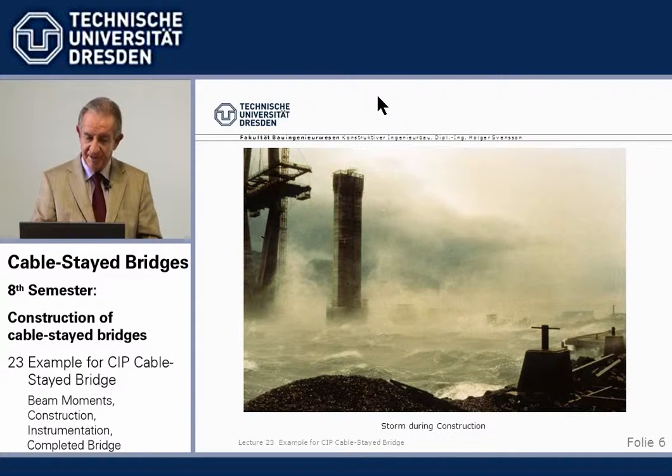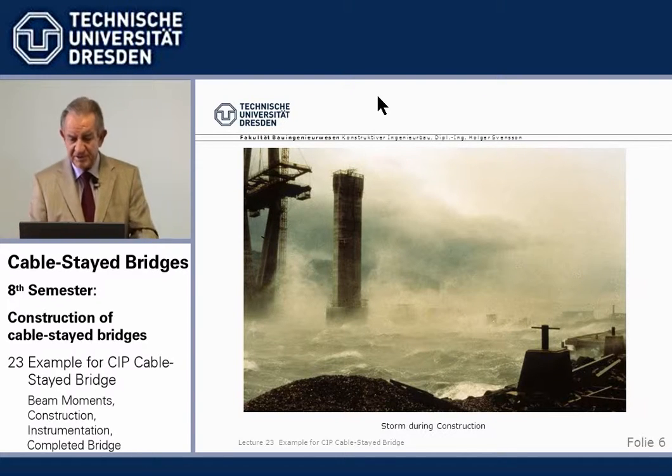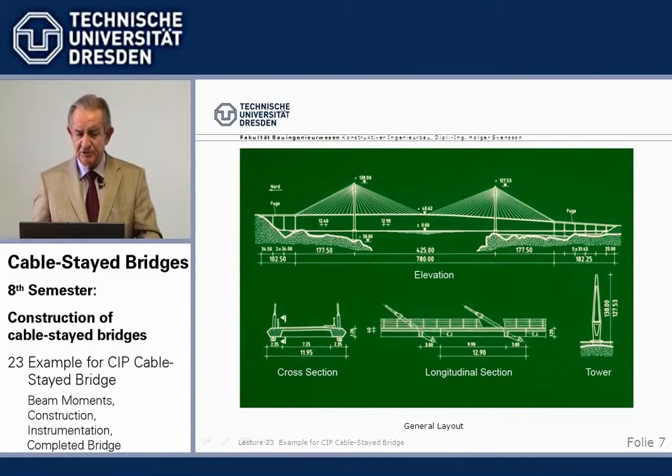That was there. Now, the bridge itself, due to the geology I showed you, had a minimum length of 425 meters. We wanted, again, because of the strong winds, as low a beam as possible, so we have little wind resistance or wind action.